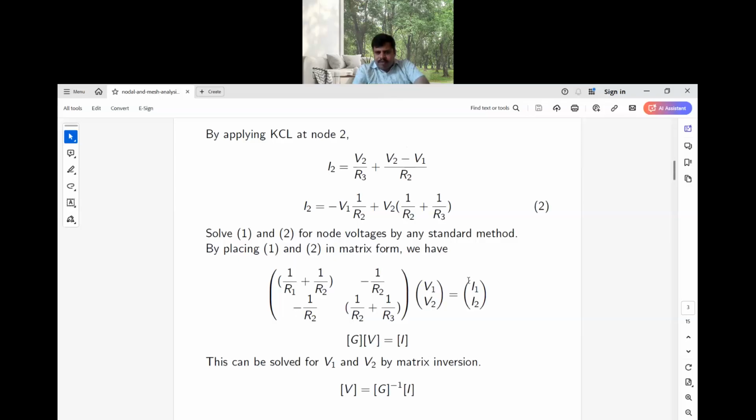The matrix of current is equal to the matrix of vectors voltage V1 V2 and the matrix of the inverse of the resistances. The inverse of resistance is known as a conductance. So we can get that I is equal to G into V. The conductance is represented by the letter symbol G and its unit is Siemens.